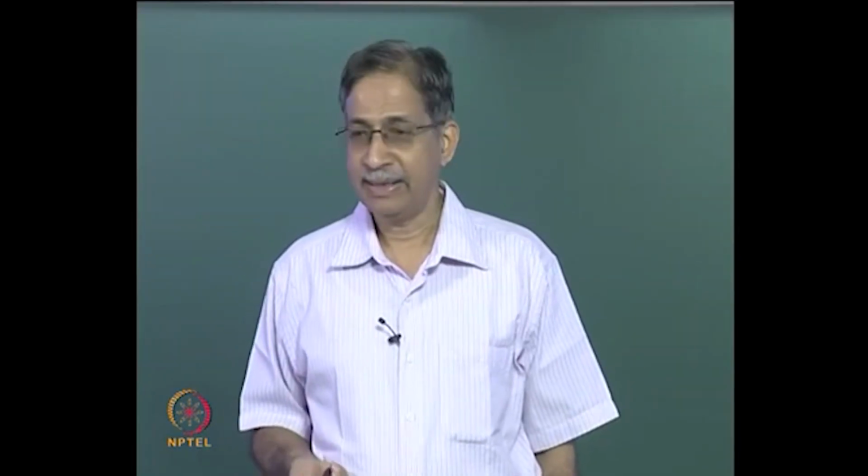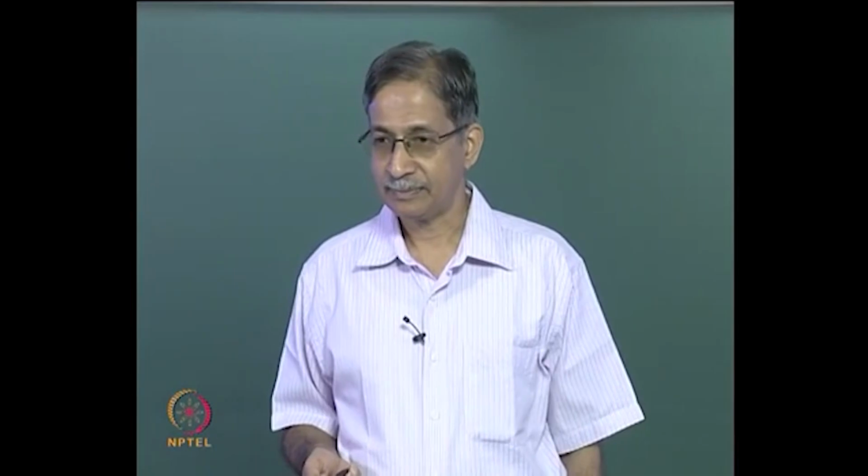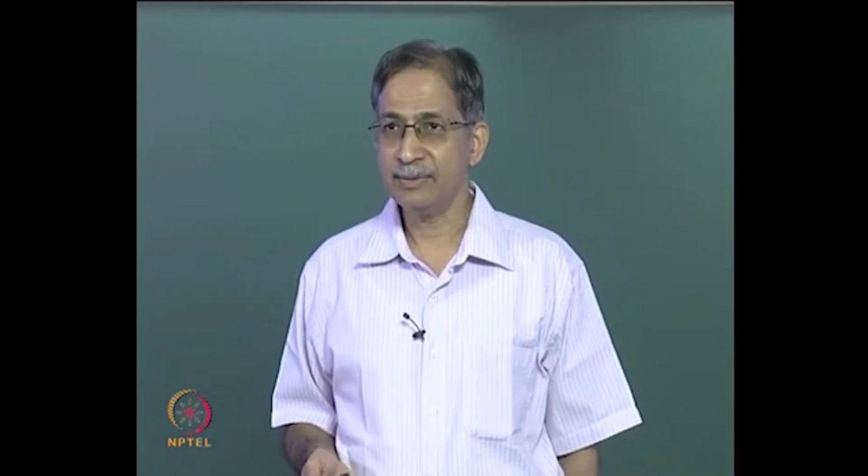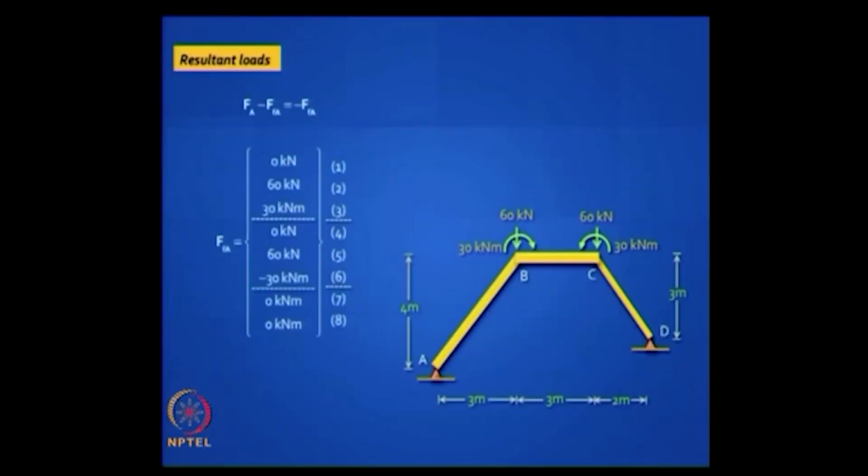You have got the load vector. What do you do next? Right, you can draw a sketch. Look at this. This is your resultant load vector. FA is equal to FA minus FFA. FA is a null vector because there are no nodal loads in this particular problem, you had only a UDL, and so FFA is given there, put a negative sign to it and interpret those results. You will find that the original problem had a UDL.